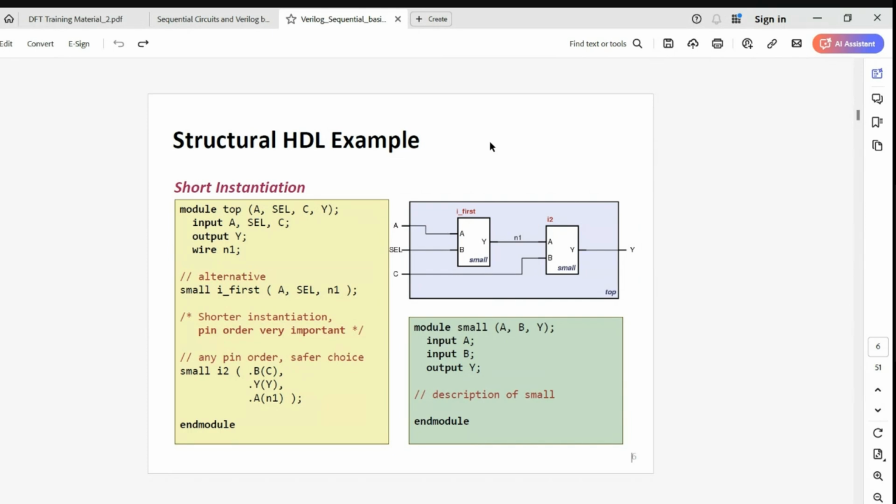Okay. So for that, you should understand the Verilog construct, how RTL construct is there and how netlist construct is there. Most of the time, RTLs will not be traced, only the netlist and the schematic will be traced. Okay. Tracing in the RTL is very difficult in real time. Okay.